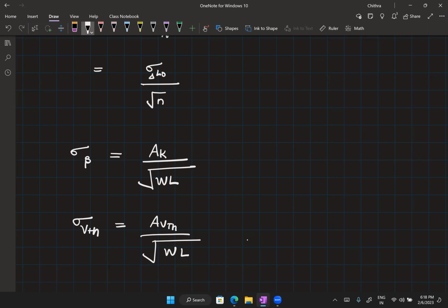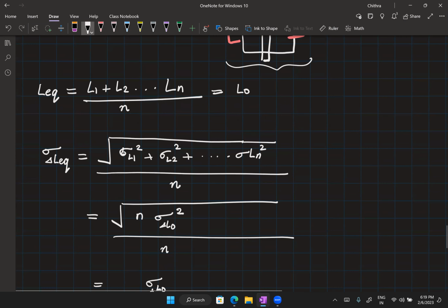So anytime you want two transistors to be matched, the first thumb rule is increase its area. You have to figure out whether it is best to increase the width or the length, but increase its area and you can bring down the mismatch between the two transistors. After you have done this in the design, when you do the layout, you lay them out identically. You make sure that they see a similar environment, etc. But all that you will learn in, I think, 613, you should be learning all these principles. Okay, so now let me come back to our charge pump circuit.